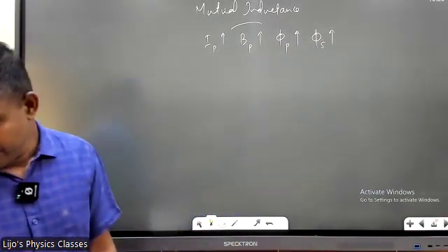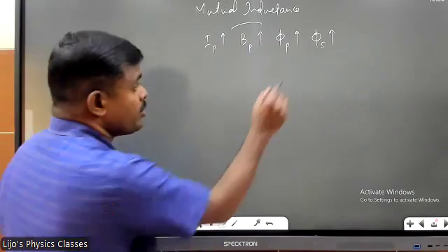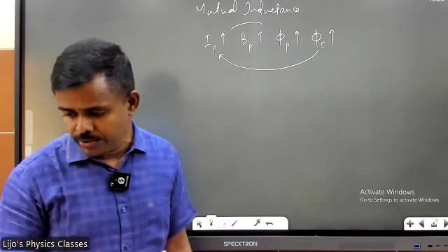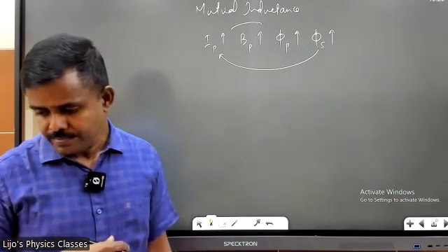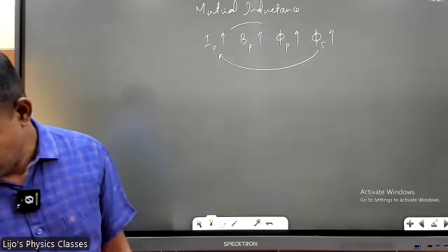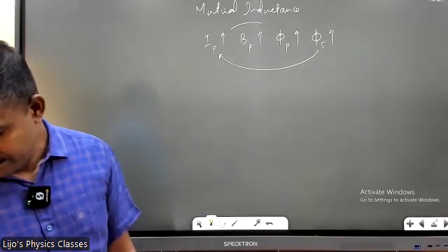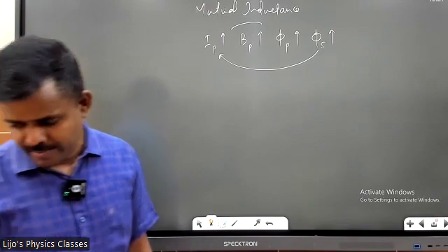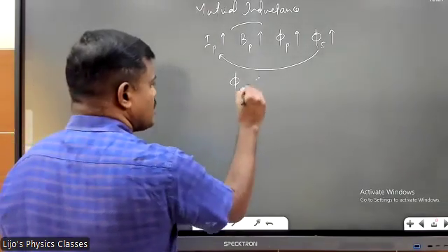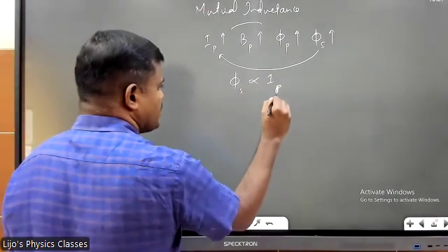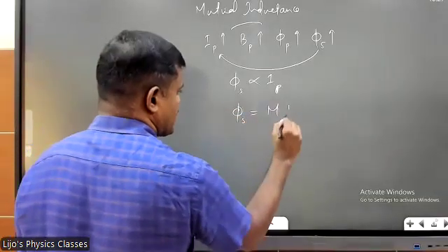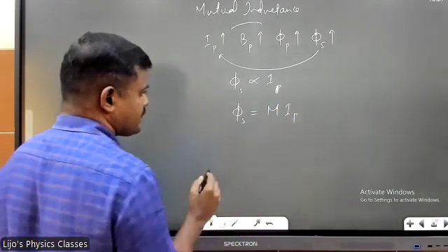Did you hear me? Right. So how can you relate them? Phi_S and I_P are related, like a cause and effect relationship, like I told you already. So you can write phi_S is proportional to I_P. Phi_S is equal to M into I_P.